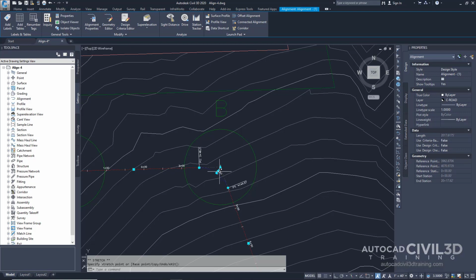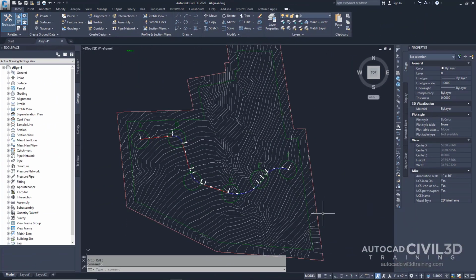Click the radius grip, which is this arrow right here. Go ahead and experiment by moving it. Notice that this grip affects only the curve radius and is constrained to the direction of the radius change. Next, select either an endpoint grip or the PI grip. I'm going to select the PI grip. Experiment with reshaping the curve in different ways. Let's grip edit a floating curve entity.